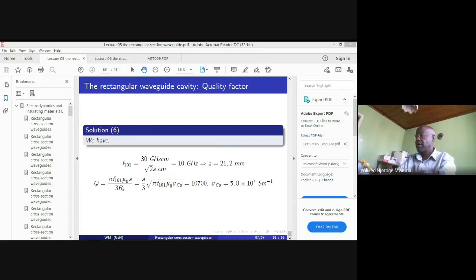Remember, as long as you are not guiding, the wave cannot be TE or TM. If it's propagating in free air or in free space, you have no problem, those waveguide modes do not propagate. The TE and TM come because we are confining the wave to propagate in a confined area, so to speak. I hope I've answered that.